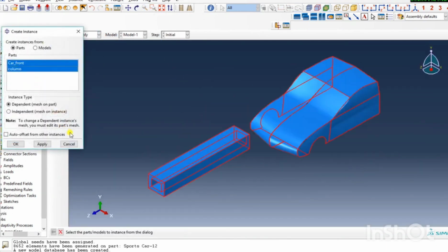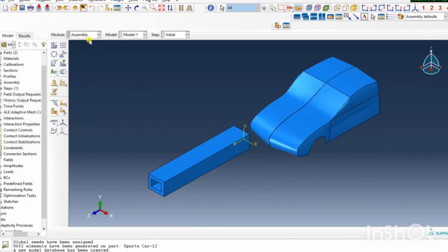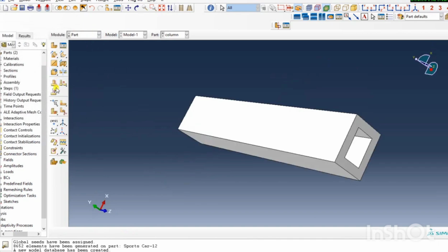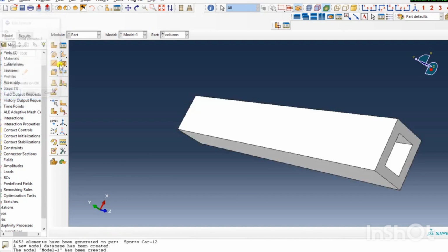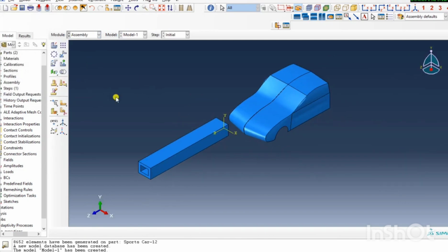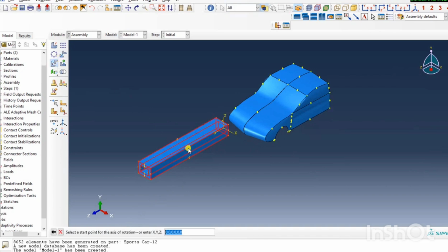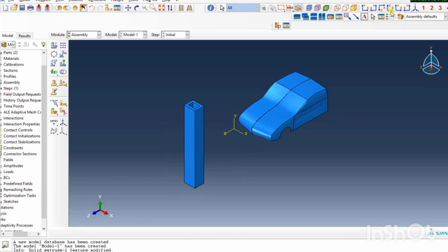The model represents a simplified axial crash member, typically used in front or rear crash structures. I have included multiple assumptions, like isotropic material behavior and rate independent plasticity, which applies unless strain rate is defined, and no failure or damage model in this case. This allows us to isolate deformation and energy absorption mechanisms without introducing additional complexities like fracture.